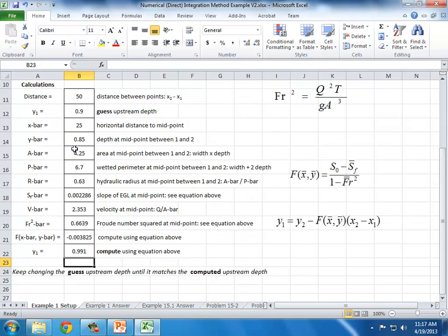Okay, so I know I haven't got the right answer because my initial guess isn't equal to the final depth. So remember how I said maybe as a first guess you can say 0.8? Well, that's worse. And so I'm going to go through this optimization process if I want this guess and this computed value to be the same, 0.95. It's getting awfully close now.